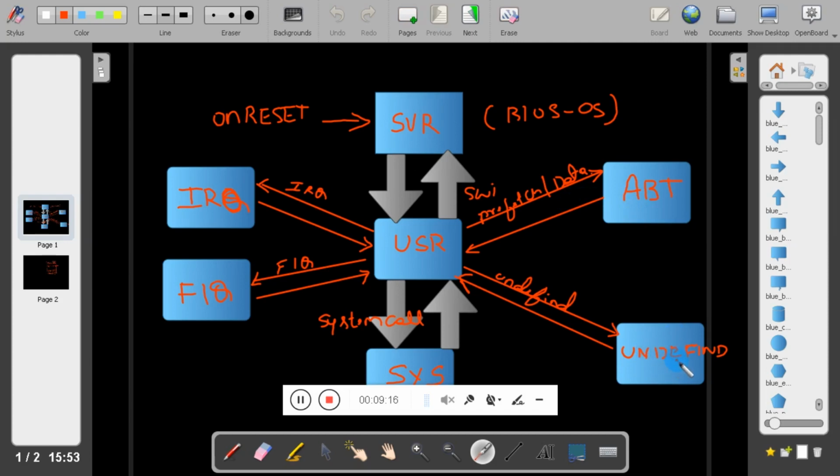For example, inside the mobile phone there will be different processors like main processor, co-processor, math co-processor, graphic processor, etc. The person who wrote the code, imagining there will be a math co-processor, and the assembler has assembled the instruction, but in reality there won't be a math co-processor. Then how can ARM7 understand the math co-processor instruction? It will automatically go to undefined mode and it will kill the application. From the undefined mode it will go to the user mode.